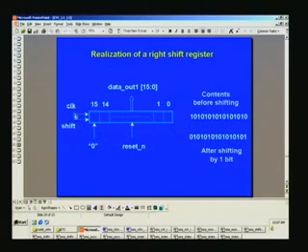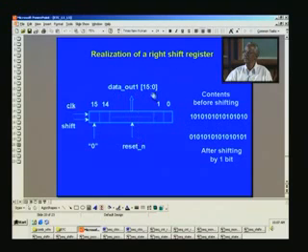So we had a 16-bit shift register, and a data out can be had here, and we had two types of shift register, data out 1 and data out 2. Both are primarily the same, except that the way of writing the assign statement for the shift was different. One was with two less-than symbols, the other one was to simply concatenate, right?